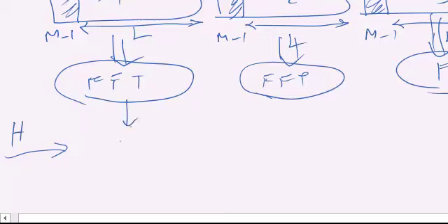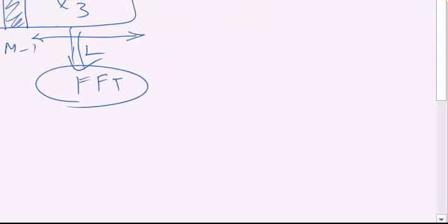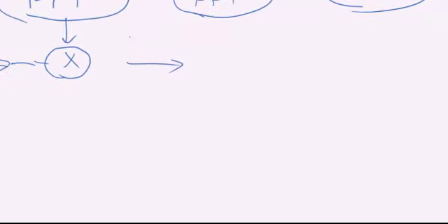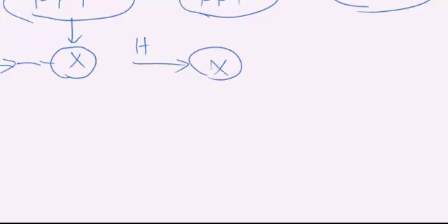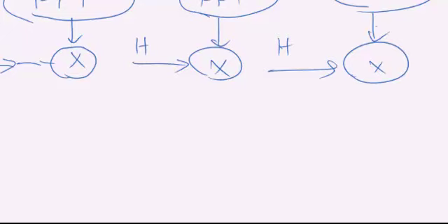Since the FFT is in the frequency domain, and let's say h is also in the frequency domain, in order to do the convolution, you only need to multiply them together. You know that convolution in time means multiplication in frequency. So we simply multiply h with all of them, and the same for here, convolution changed to multiplication for all of them.